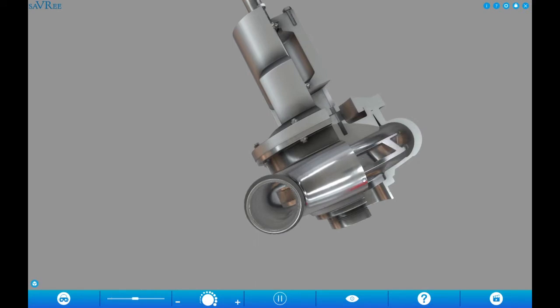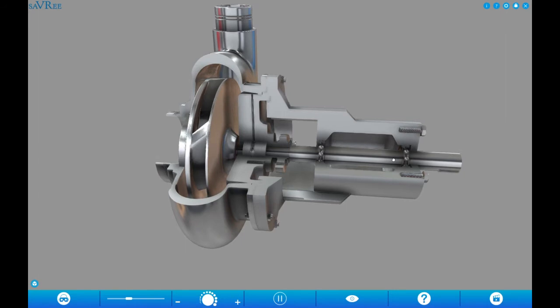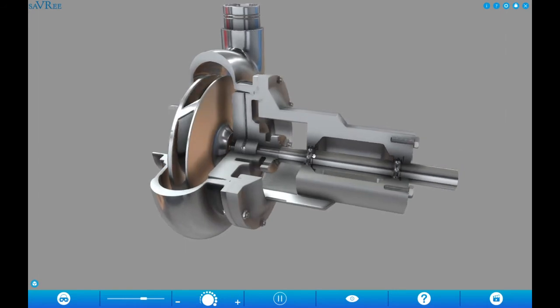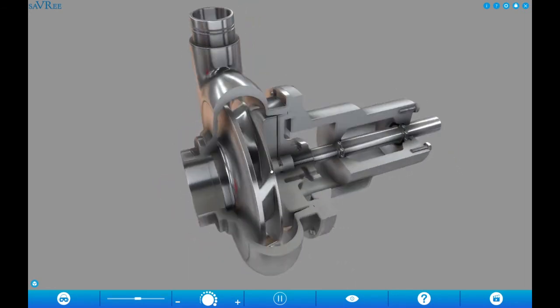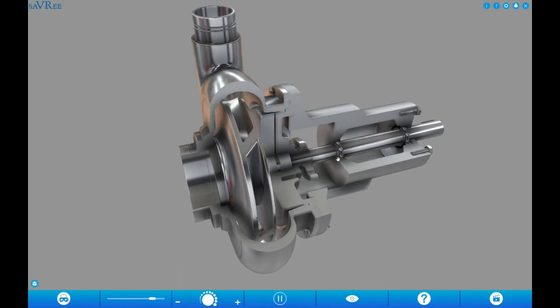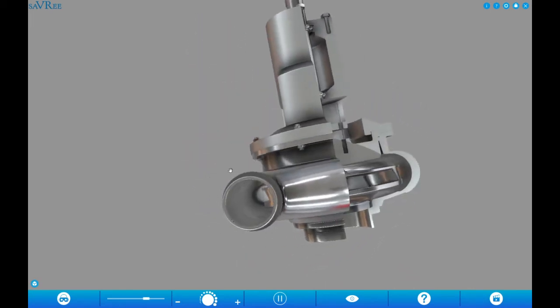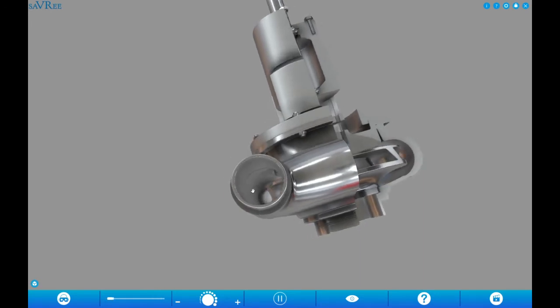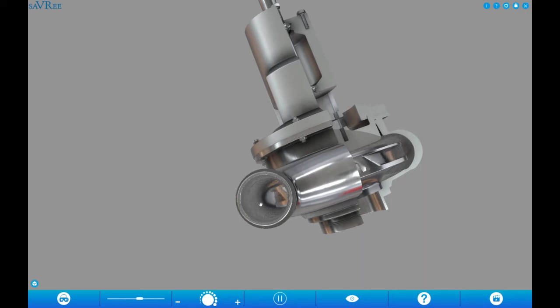So the pump will directly push the water outside, and all the radial forces will be acting on this shaft. Once the radial forces act, it will also affect the life of the bearing and the mechanical seal. All of these components have some rated radial force acceptance, so they can accept up to a certain level. That's why the smaller range of such pumps will come without any vane, or we can say a pump without a partition, or no double volute is given.